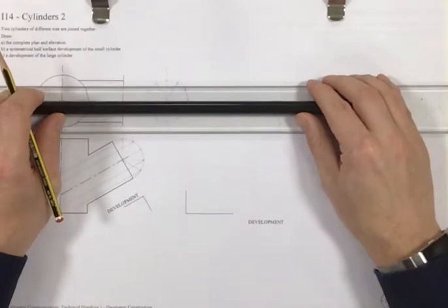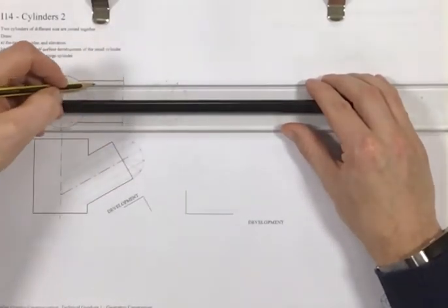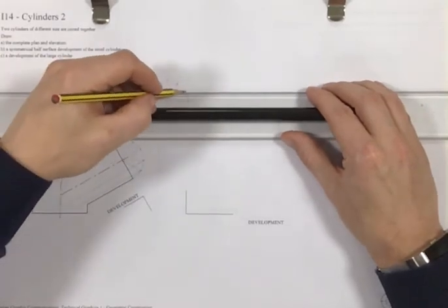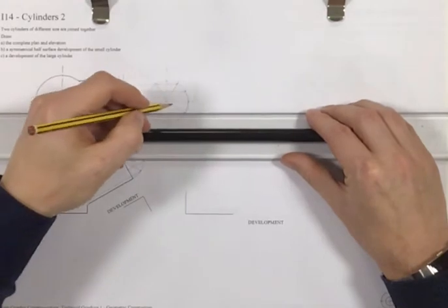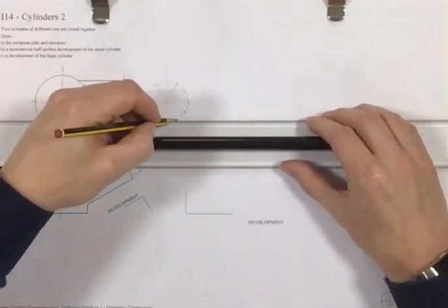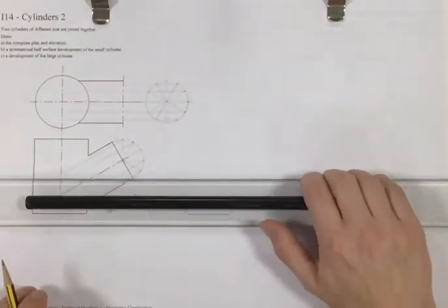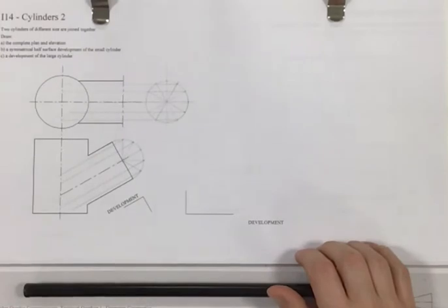So in other words, at 30 degrees, I just want to bring these points, and we're just using construction lines here, not too heavy. And we'll just bring them all the way down to the centre line. They won't go as far as that in the end, but it's just for construction work. Likewise, we want to do the same here. So we're wanting to bring these points across. That line's already there. This point and this point. So we have a range of construction lines that we're wanting to work with.